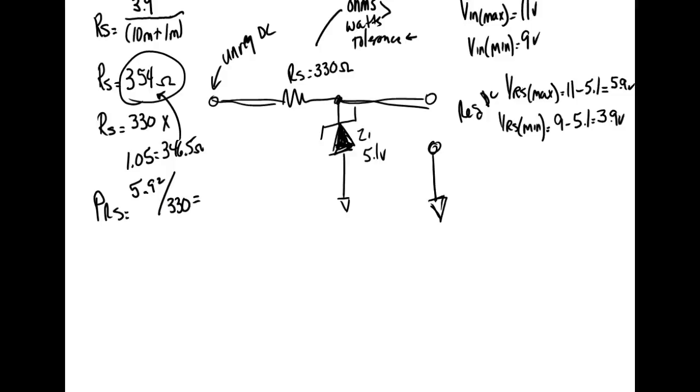That's one of our power formulas, V squared over R. And by George, you should have those formulas in your head. Ohm's law. When I ask what I is equal to, you shouldn't even think about it. You shouldn't have to write down the little color wheel. Your Watt's law and your Ohm's law should be in your head. Now the derivatives of Watt's law are pretty complicated, especially when you get into the V squared and the I squared. But what are the three main power formulas? P is equal to what? V times I, I squared R, and V squared over R.